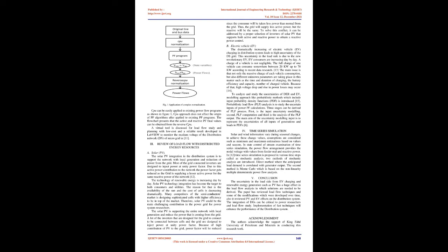To solve load flow using NR will only require a few iterations, thus NR is mostly used for highly complex systems. On the other hand, in NR the Jacobian matrix has to be calculated in each iteration, so some concern of time and storage takes place. To overcome this, a modified version of NR was introduced later to abolish ill-condition in LU factorization. Fast decoupled, FD, technique can be performed to find solutions regardless of the size of the network. In fact, it is an extension of NR method which leads to fast algorithms of PF solutions.